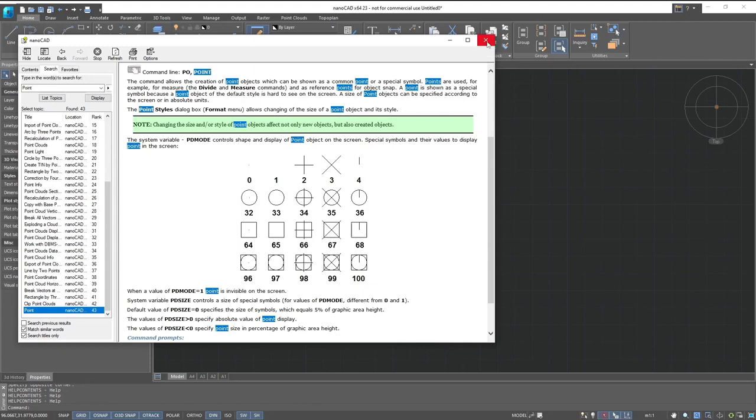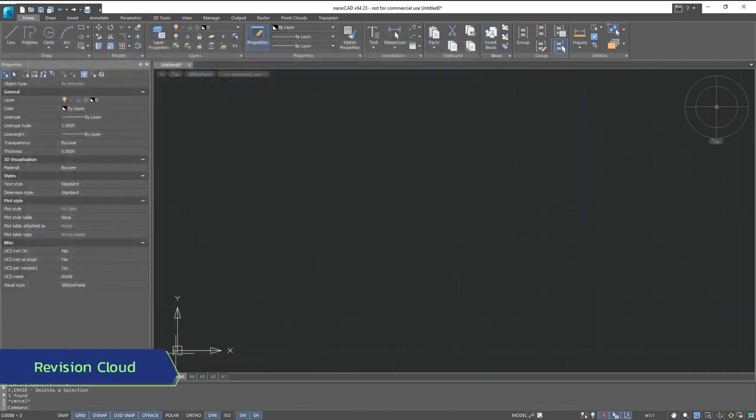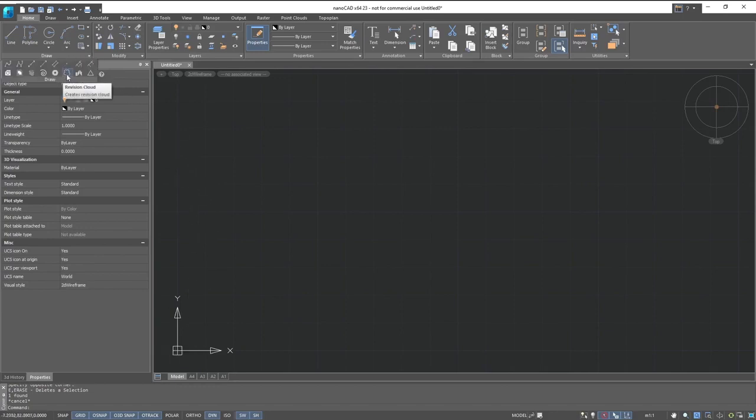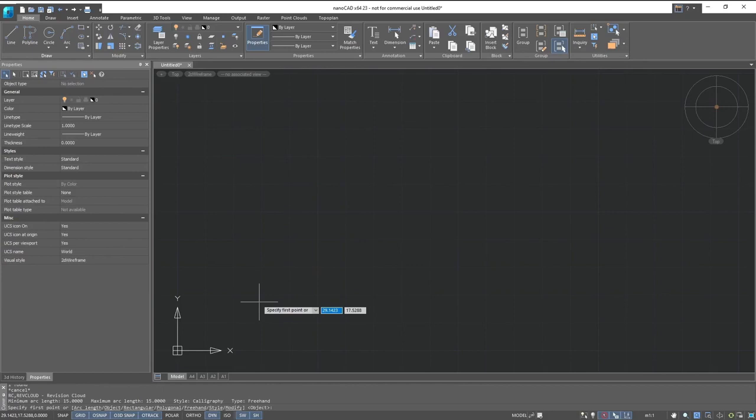And that is it. The next drawing mode is revision cloud. The cloud consists of arc segments, the length of which we can adjust. More often than not, the cloud is used to highlight explanatory notes or to make markings on the drawing. The cloud offers many parameters that you can use, some of which we will apply. Let's leave the arc length unchanged and do the first construction.